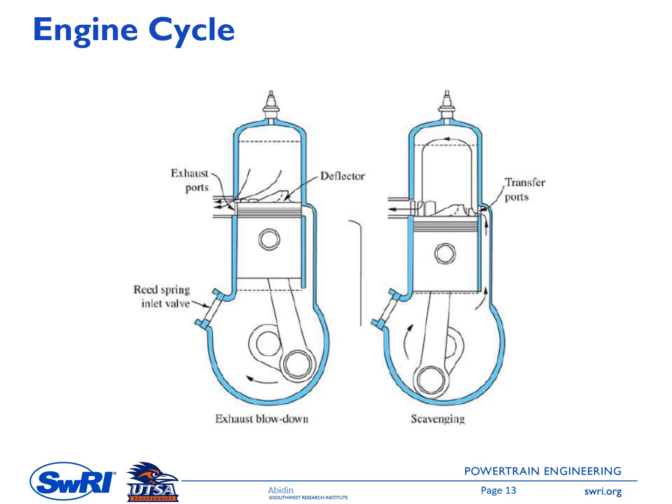Let's take a look first at the left figure here. At this condition the piston has moved down. So imagine at some point the piston might still be at this position. When that is the case, the piston moves down doing the expansion process, or the power stroke. And then at some point the piston will be at this position, and you can see in here there are two ports, one port on the left side and the second one on the right side.